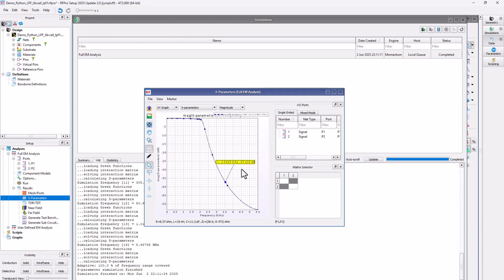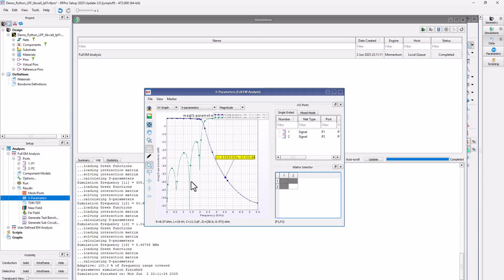So again, if you had a dielectric with better properties, like better loss tangent or something, you could have hoped for a little higher rejection at that frequency. But this is not bad as a starting point. If needed, you can optimize your design and obtain the required attenuation or change the filter order a little bit. We can also plot S11, which also looks pretty decent, better than minus 15 dB of return loss till the pass band frequency and so on. But you can see you have a very good start point now to fine-tune the design the way you want and then be more productive instead of doing repetitive things all the time.